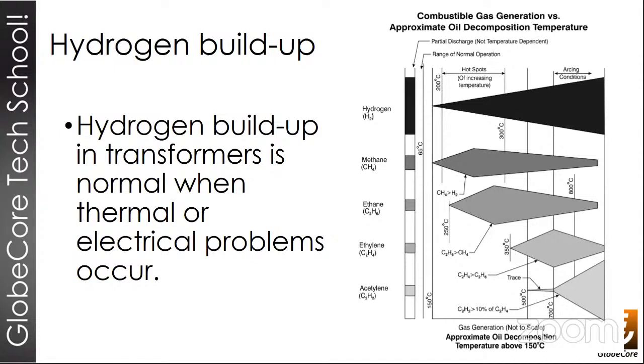And when studying faults of greater intensity, we use characteristics of gases for which a lot more energy is required, but we will still always register continuous increase and buildup of hydrogen. And this is why there is a series of sensors that only monitor hydrogen level. This allows us to know if there is a change in the operation of the transformer. It's also usually a gas with one of the highest concentrations in chromatographic studies. So knowing the amount of hydrogen in oil is a very good indicator that allows us to determine the state of thermal vacuum processes and degassing processes as well for the oil.